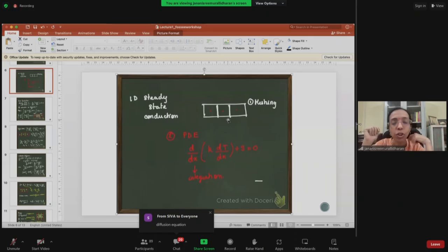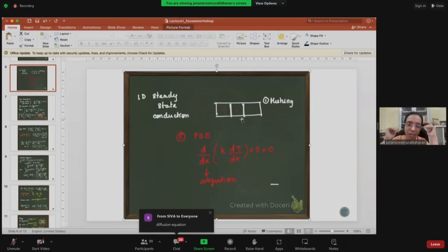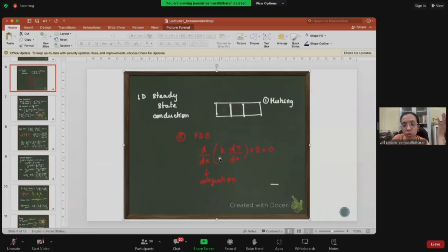Yeah, good, Shiva. So essentially, conduction is a diffusion-based equation, correct? So this is something that you see over here where there is a diffusion term, okay, and a source term added to it. So diffusion in itself means Laplacian. So the solver is purely a diffusion-driven solver. And we're going to show you how using this new solver, you can model simple conduction problems, okay?